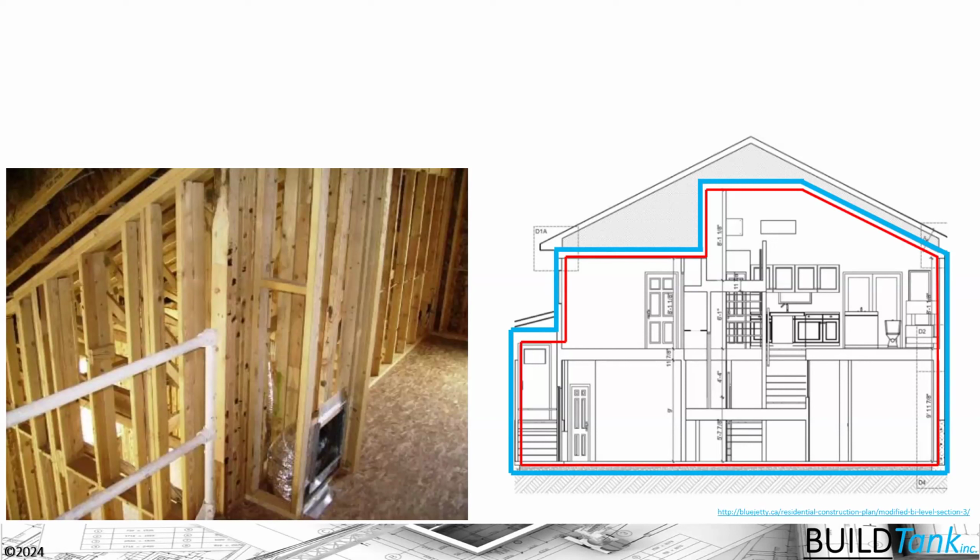You could type in an answer to that question in the chat so that we get a little bit of understanding of what you're thinking. But I'm going to move on pretty quickly and tell you that we want that duct to be inside the building envelope. In order to do that, we're going to insulate this wall. We're going to insulate behind the duct, and we're going to insulate down the wall of this loft area as well. And then maybe we're going to sheathe the attic side of that assembly to help create that boundary between conditioned space and unconditioned space.